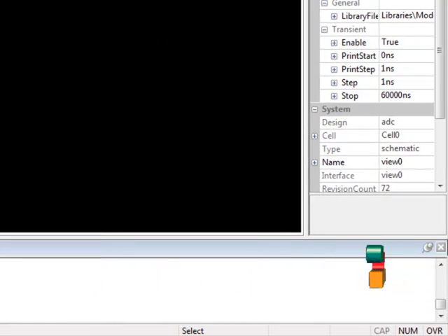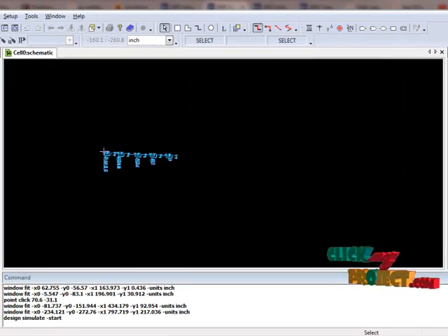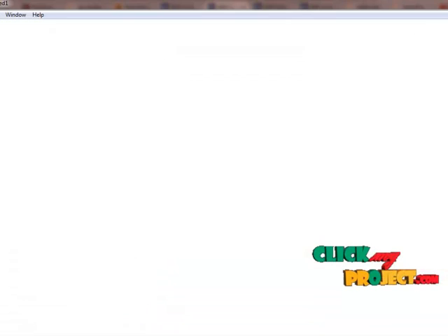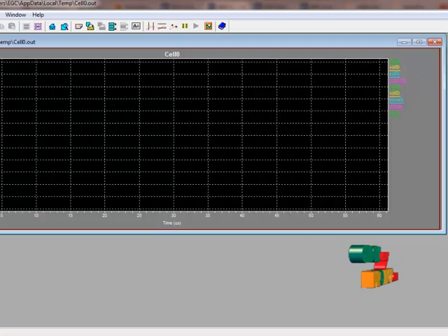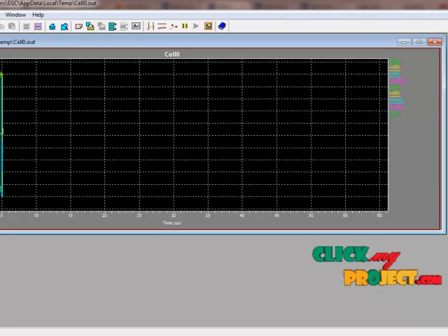After running the simulation, the waveform editor tool opens, and we analyze the graphical output changes as zeros and ones. Here we are using our analog-to-digital converter. We give the analog values and we get the digital values as zeros and ones.